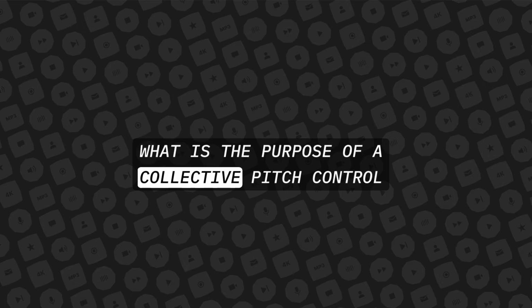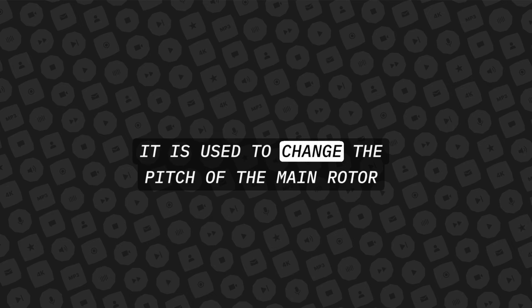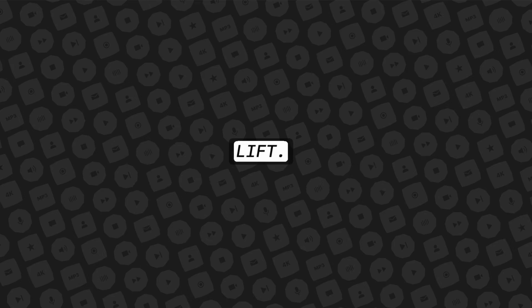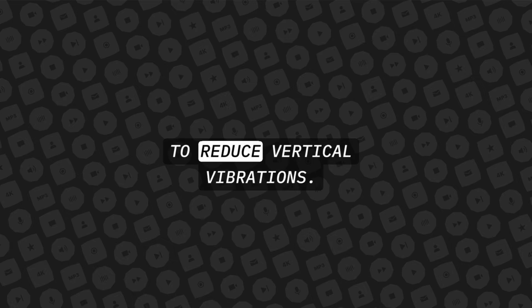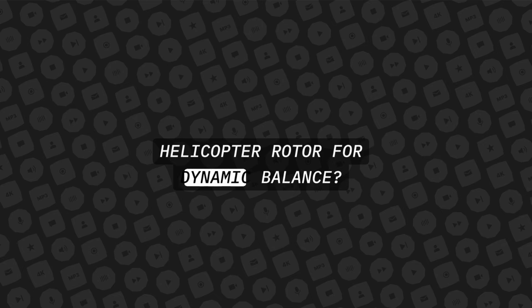What is the purpose of a collective pitch control in a helicopter? It is used to change the pitch of the main rotor blades, therefore increasing or decreasing lift. Why is it important for the blades of a helicopter rotor system to be tracked? To reduce vertical vibrations.